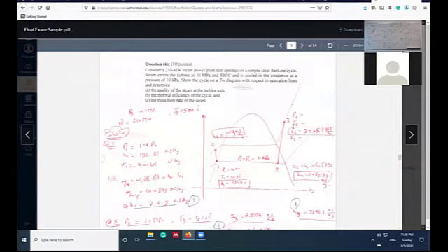No worries. So we said at stage 3, because superheated and vapor, A4 for input temperature, saturated mixture, A5 saturated mixture for pressure input, A6 for superheated. So at this pressure and this temperature, you can get H3, S3, and so on. S3 was 6.59. It's the same S as 4. Why? Because this is turbine, isentropic expansion. You have the steps. This is open book. You have all the steps from T3 to 4. S3 equals S4. And you have pressure 4. So you can easily get X4 because you have SG and SF. You can get X here.